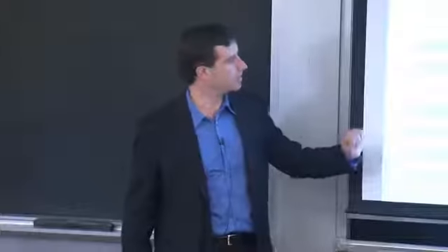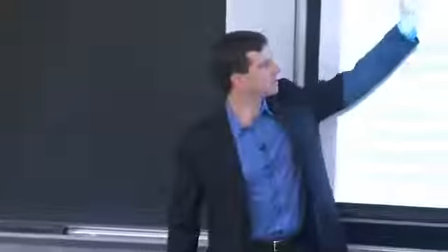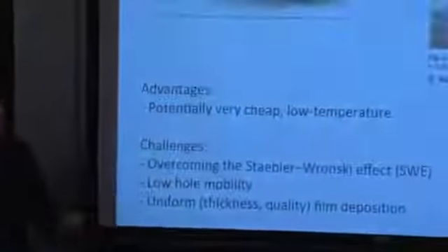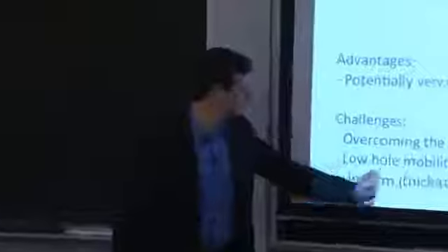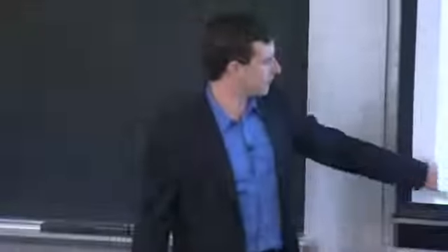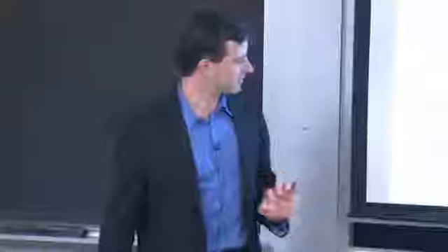So when you report the cell performance of an amorphous silicon cell, it's always very important to emphasize that this is light degraded or light stabilized efficiency, as opposed to the efficiency you get when you take it straight out of the deposition chamber and it hasn't been exposed to high amounts of sunlight yet. In general, amorphous silicon has low hole mobility. Again, the precise root cause on an atomic scale for the low hole mobility is still up for some debate.